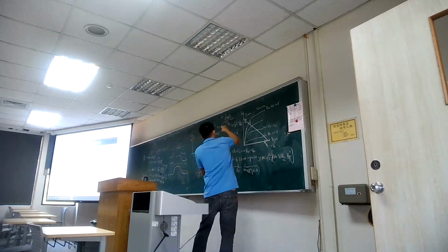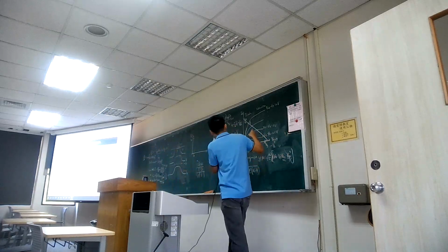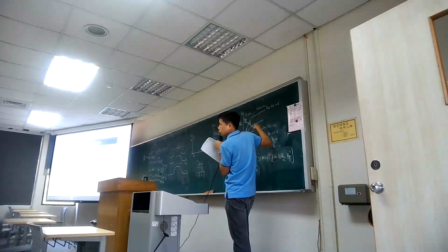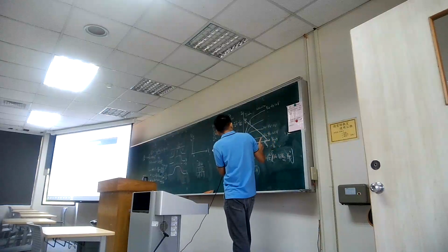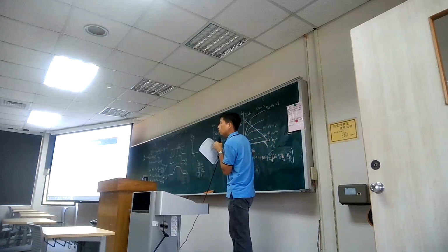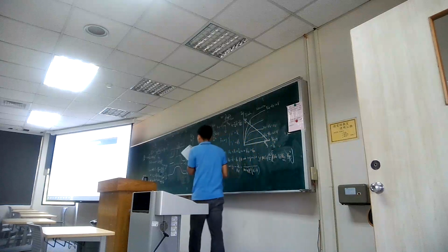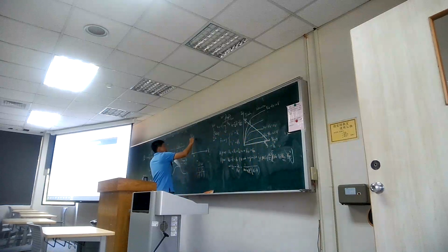So here's the VDD. But when we have the current flowing through the RD, it continuously provides the ID and drops the voltage at the output. So you can see the current start to go up, and then the output keeps going down. So what happens here is in the saturation region. Again, remind you, for a BJT it is the active region. So here we have the saturation region.